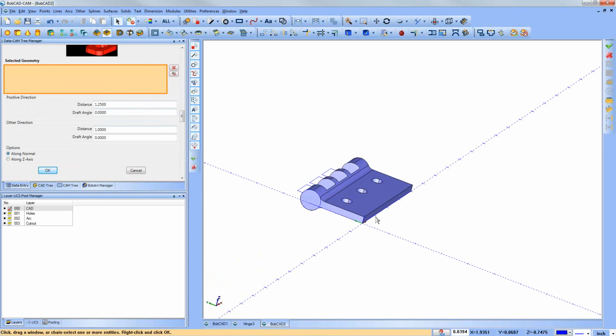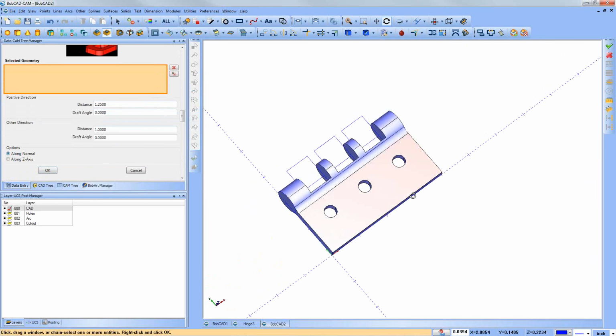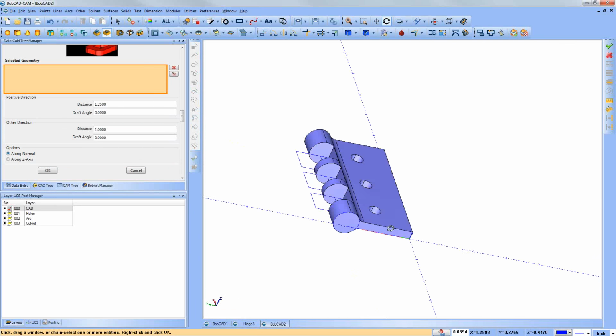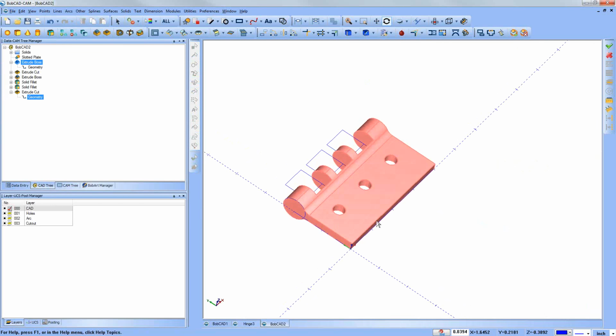Moving on, so I'll select this cut. Okay, so I have a cut here, and what I can see is it cuts through this back part of the thing, and we're almost there. What I want to point out at this point, I mentioned the holes, how I put those in a separate layer so I could modify them. I'll actually modify the geometry that I have here, because if I'm not satisfied with what I have as I keep building up this part, say this extruded cut is not quite where it needs to be, it needs to come down more.